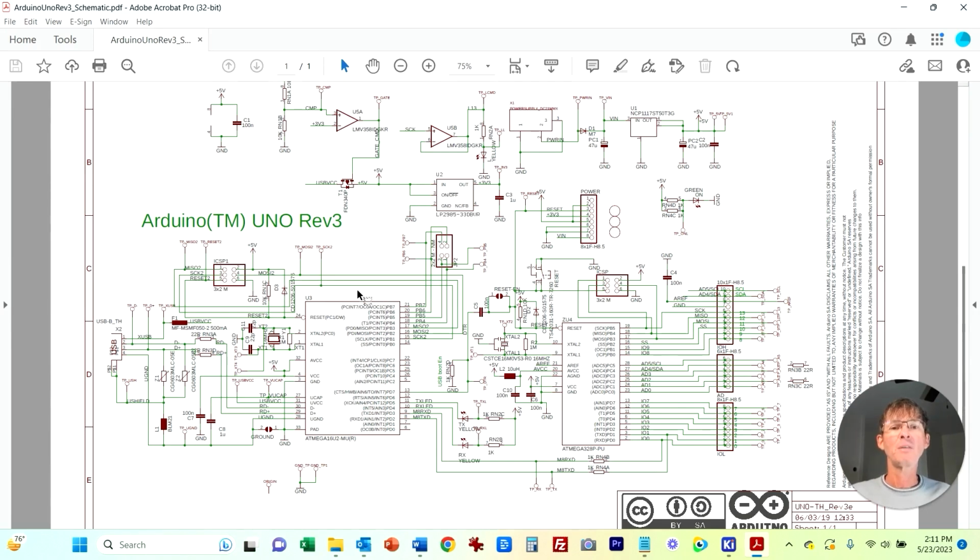This is kind of Arduino Uno specific. Now, other Arduino boards that still use ATmega 8-bit microcontrollers, like the Leonardo, have basically eliminated this two-microcontroller issue, and instead they've gone with the ATmega32U4, which is in this same family. So it includes a built-in USB port, but it has more memory, so it eliminates the need for the second microcontroller. However, it's a pricey microcontroller.